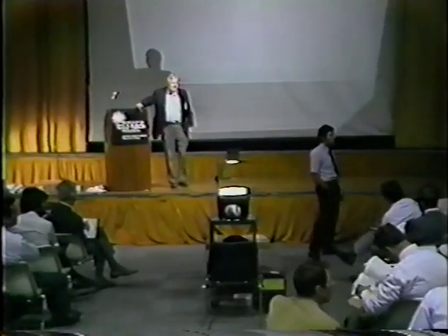Hello. Huggins, Stanford. Nate, I noticed that you annealed at 300 degrees centigrade, or 350. For a material like palladium, this is certainly not anywhere near high enough temperature to get interstitial impurities out of the octahedral or the tetrahedral sites.